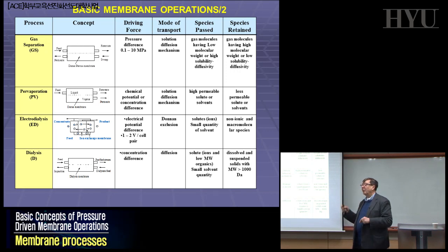It is 1 for sodium, and 0 for chloride. That means in these membranes, 100%, or 98%, of the current is transported by Na plus and not by chloride. If the transport number is 1, it is a very effective cationic membrane. If it's 0.5, you put it in the garbage because it's not very good. It's the same as in solution.